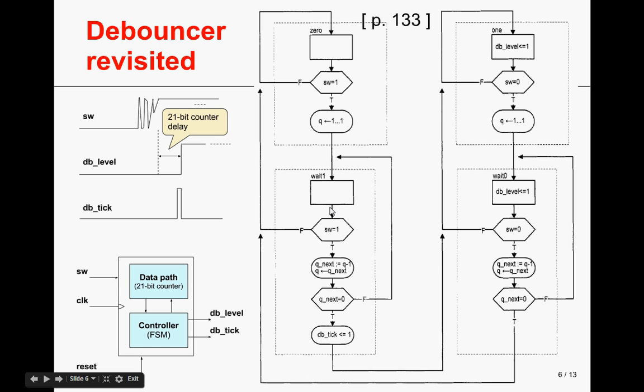There are no outputs to assert, either in state 0 or 1 in what concerns Moore outputs, so the state boxes are empty in these ASM blocks. Now, while we are at state 1, we will continuously check the input coming from the switch. And if it happens that we read a 0, the whole thing will restart.